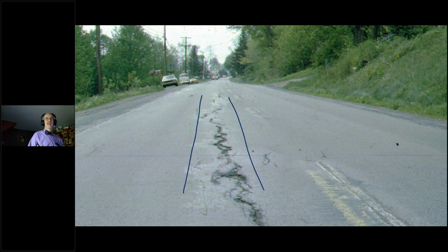And that's the challenge, obviously, from a photograph. But the key here that I want you to be thinking about is what's causing the underlying distress. Usually that's where we need to focus our repair. What's causing that cracking in the first place? If we can figure that out, we can probably pick the correct repair. I happen to know this road. It's not too far outside of Ithaca. And the real problem here is actually the fact that we're on a side hill situation and the road goes in, and I'm going to change my pen color because it'll work better that way.